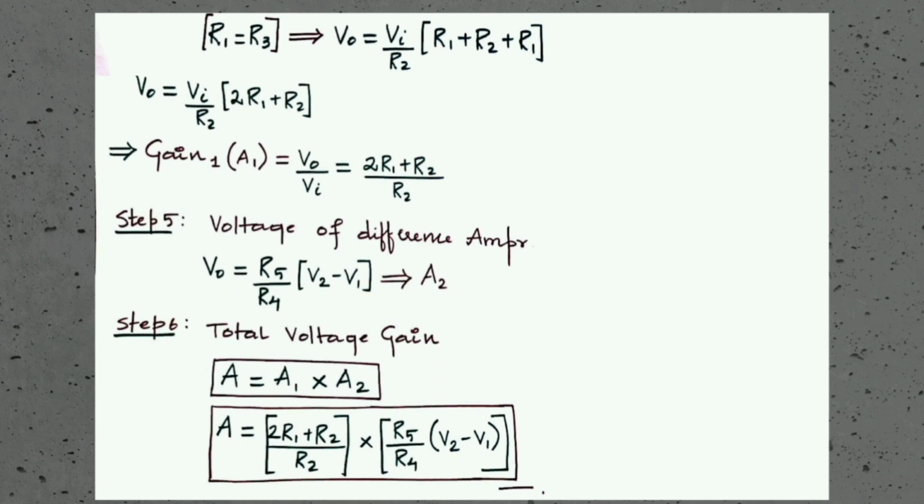We can note down a few applications of the instrumentation amplifier. Number 1, instrumentation amplifiers are used in data acquisition from small output transducers like thermocouples, strain gauges, and measurements of Wheatstone bridge, etc. Second, these amplifiers are used in navigation, medical, radar, etc. These amplifiers are used for imaging as well as video data acquisition in the conditioning of high-speed signals. They are also used to enhance the signal to noise ratios in audio applications like audio signals with low amplitude. And these amplifiers are used in RF cable systems for amplification of high frequency signals.